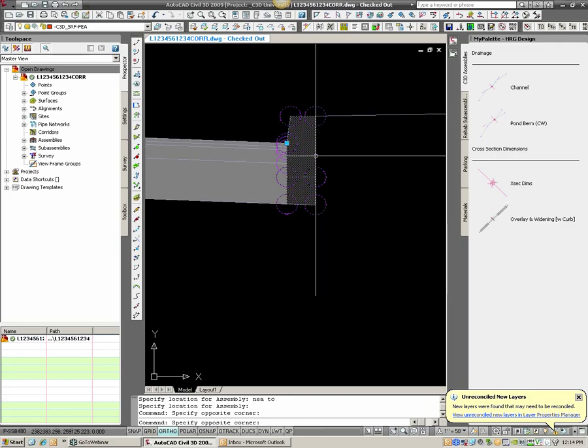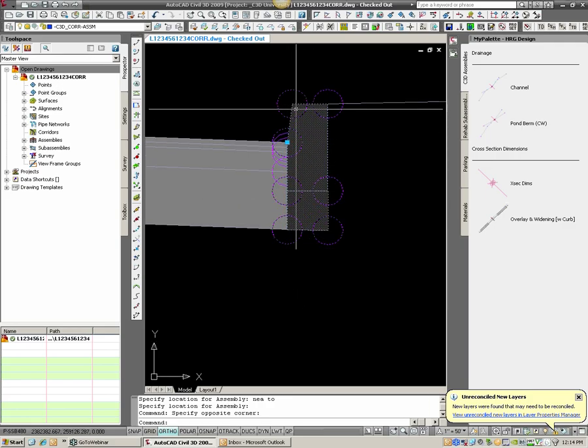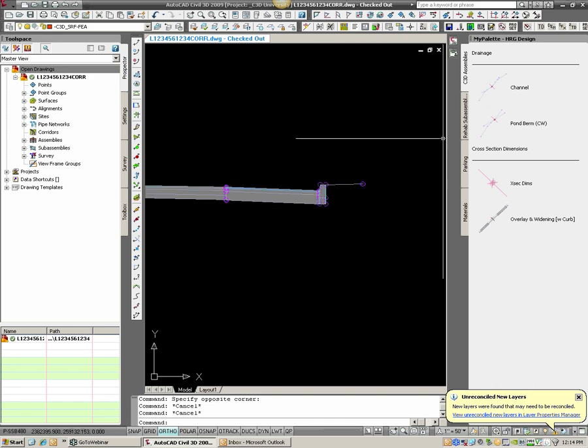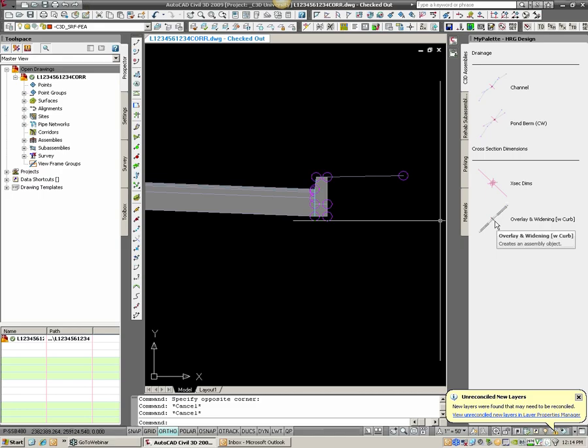He set this curb up already. He has the appropriate height and the setback for the curb deflection and so on and so forth, and the subgrade. And I'd like to use that. If I just grabbed one of the Civil 3D generic curb subassemblies, it wouldn't have all the numbers set up in it, and I'd have to go through and really have to know that subassembly, set all the variables appropriately, and then go from there. Well, I can save that time if I just pull off any of these.